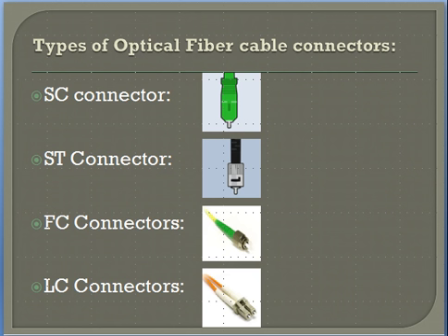ST stands for straight tip, a quick release bayonet style connector with a long ferrule. STs were predominant in the late 80s and early 90s, and it is the common type of connector for multi-mode fibers. And the third type of connector is called FC connector.